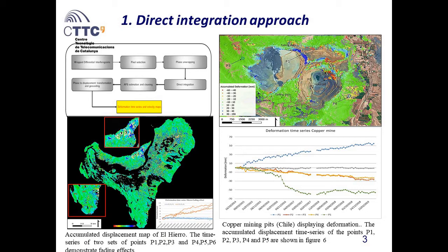The figure shows an interesting area affected by displacement with a corresponding deformation time series. These deformations are related to slope instability along the open pit resulting from excavation and the mining exploitation. This method does not have a quality estimator. It is worth noting that despite these potential errors, the target of the analysis is fulfilled since it provides enough information to detect active areas.